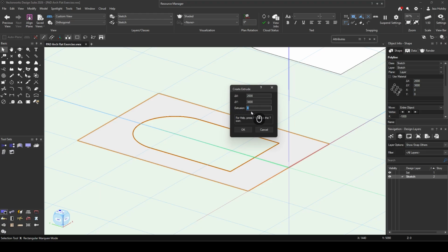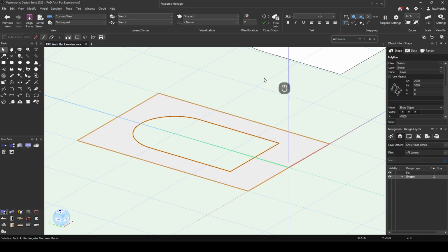At the moment it's saying 0, so I can extrude forward and back on that Z-axis, or whichever direction it was facing. I extrude in a plus, so extrude forward, or extrude back, up or down, depending on the orientation of your object. That makes sense. So for this extrusion, I'm just going to hit cancel for now.